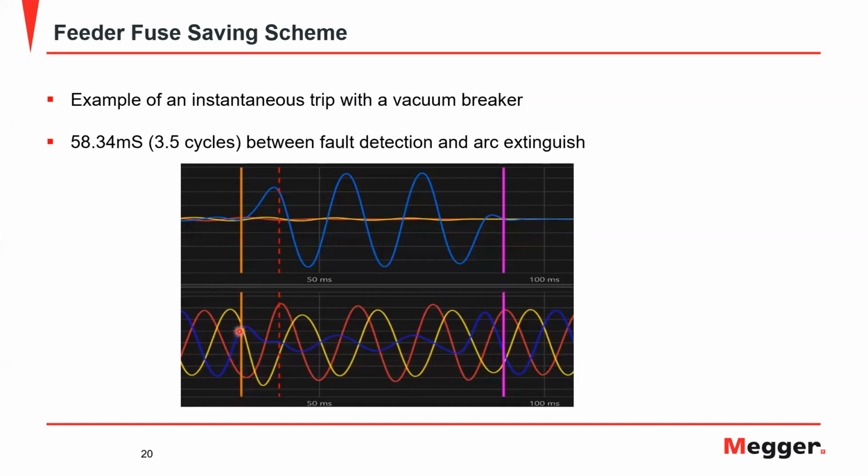Voltage decays immediately. That's how you can usually tell the exact moment that the strike occurred. Current rises quickly as well. Throughout the fault, you can see voltage is maybe 30 to 40% of nominal on the faulted phase. The other two phases are a little bit affected, but they're almost normal. Okay.